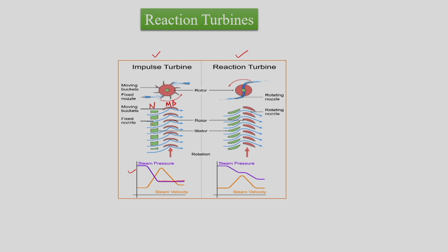The flow in the impulse turbine is such that the velocity is directly hitting. The velocity vector is arranged such that there will be a stagnation point here, which would lead to action or an impulse on the moving blades, and then the moving blades will rotate. However, in case of a reaction turbine we will have smooth flow into the moving blades.